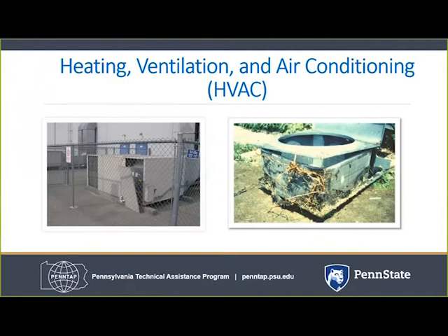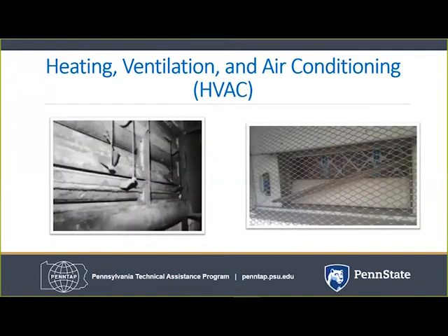You can also consider bigger changes to your equipment to improve efficiency. For example, investing in an economizer can allow the use of outside air for cooling load when conditions allow. Some other common maintenance issues are broken or disconnected linkages and jammed or frozen outdoor air dampers.